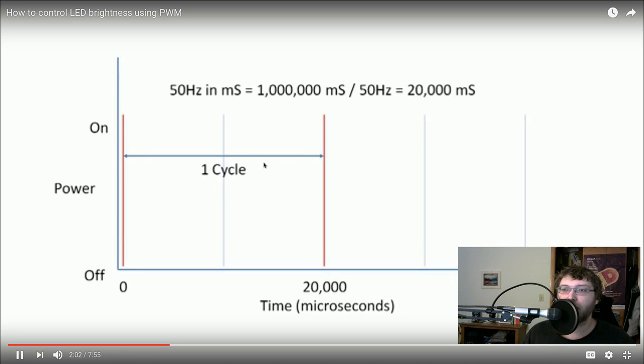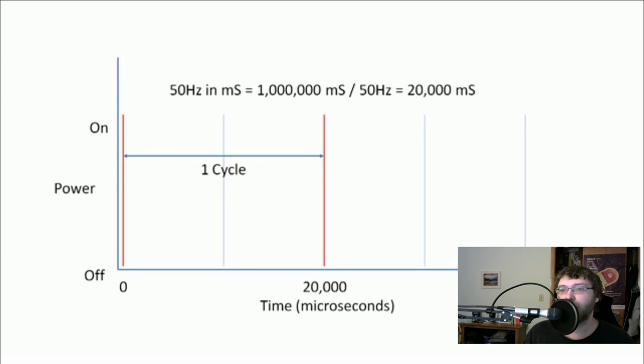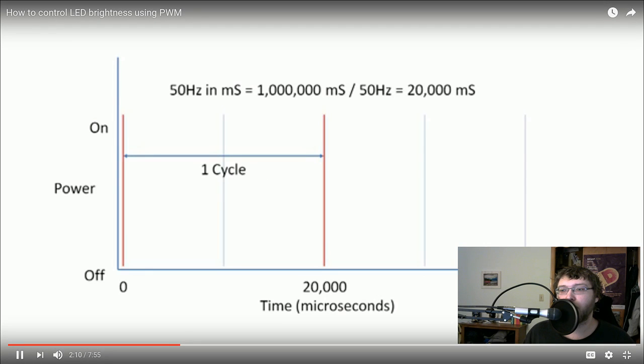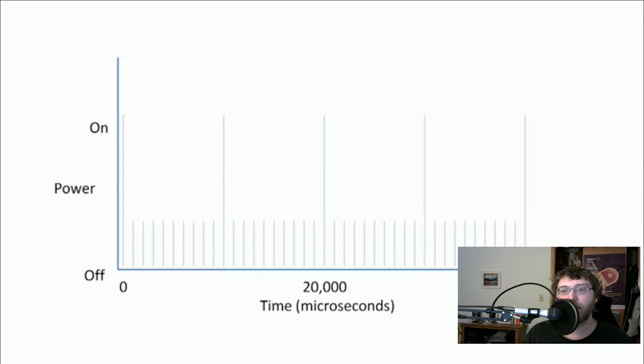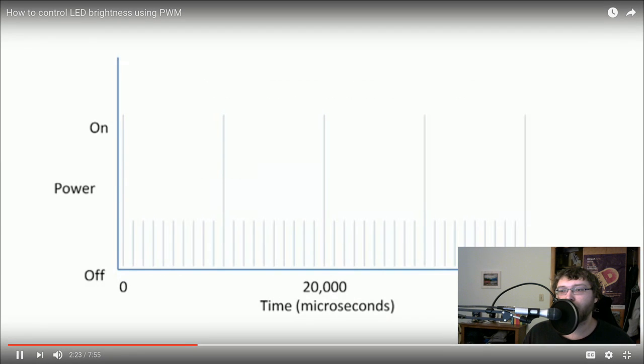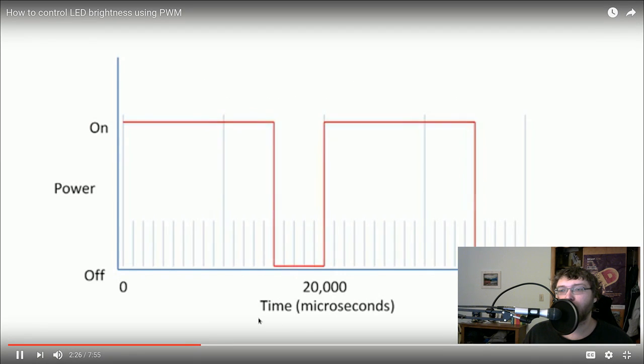At 50 Hz, our cycle is 1 second divided by 50 cycles, which is 0.02 seconds per cycle. Since we are using such small time measurements, it's more useful to use microseconds. There are a million microseconds in a second. This gives us a cycle duration of 20,000 microseconds, which is 50 cycles per second, or 50 Hz. During the 20,000 microseconds, we have to turn the LED either on or off depending on the required duty cycle. So for example, a 75% duty cycle requires the...